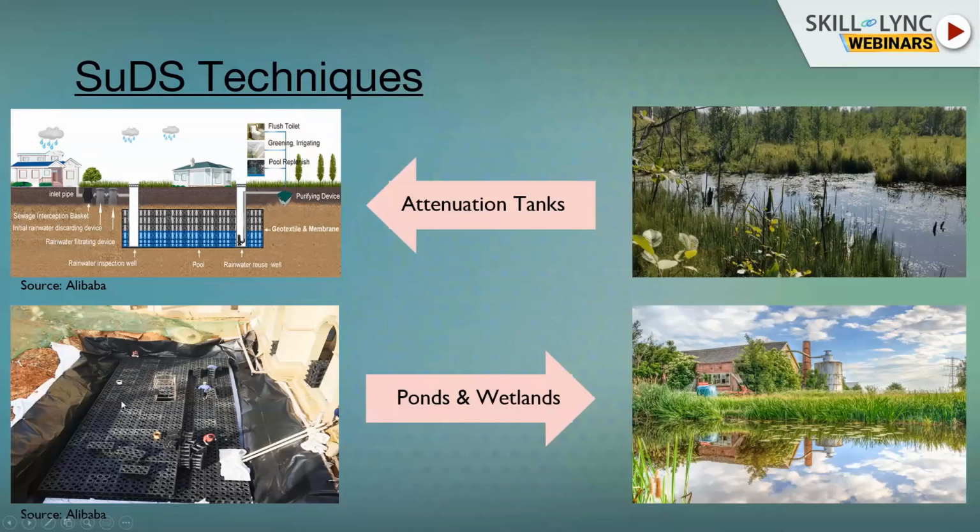Sometimes, if the infiltration rate of the ground is very good, we try to use that. If we are considering infiltration, the size of the tank gets reduced. Basically there we have just one inlet and two outlets. One is going to the public sewers and one is going to the infiltration. So the size is greatly reduced.